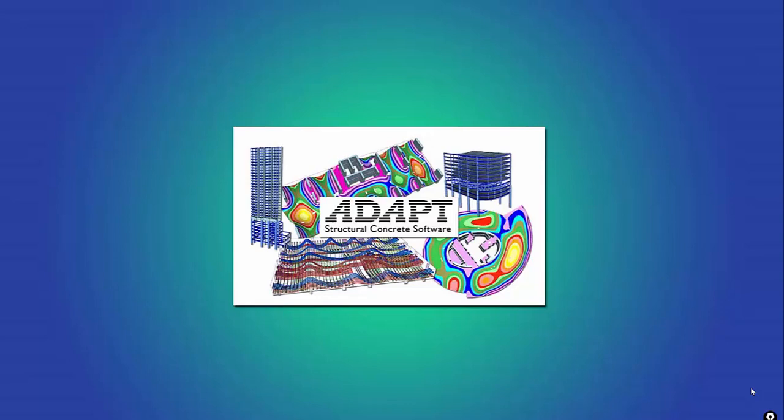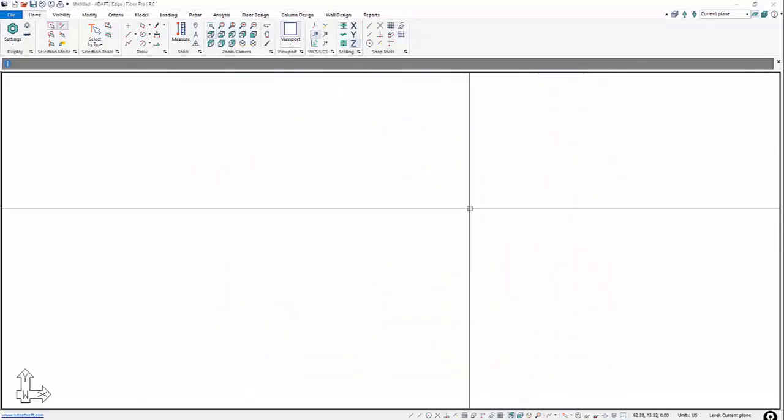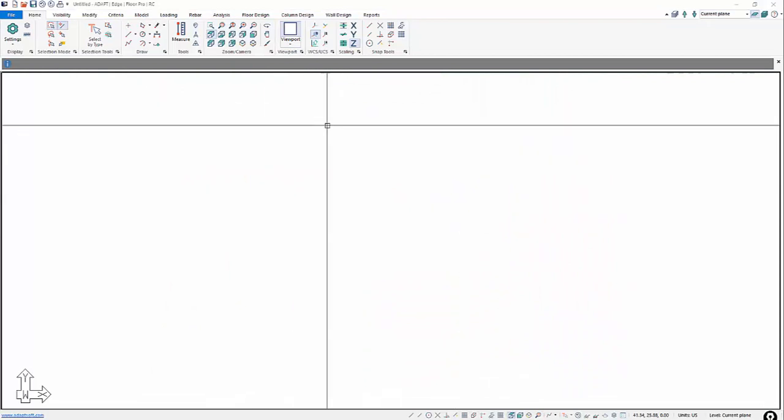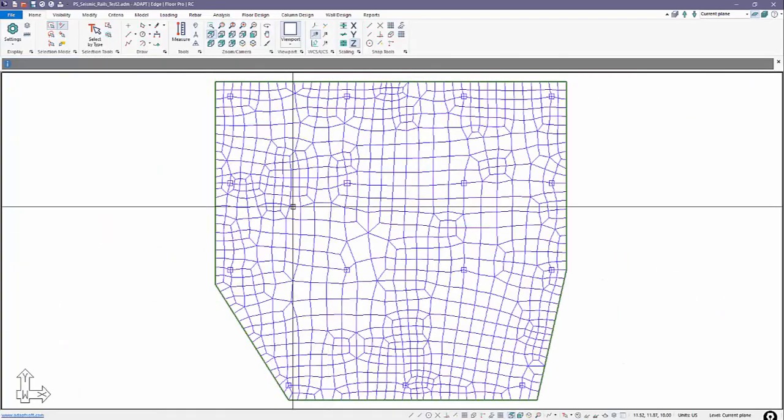In this video, we're going to give you a sneak peek into a couple of new improvements related to punching shear. These are specific to the ACI code in the software. We'll go ahead and open a model here and get started. This will be a two-way flat plate that's reinforced. There's no post-tensioning. The same improvements apply to a PT slab also in their implementation.